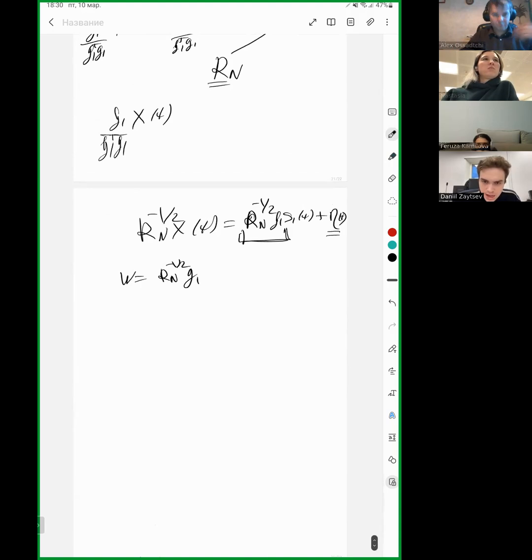Of course, you can reformulate beamformers for cases where you never have a single source. You always have multiple sources, right? And all you have to do is somehow distribute the degrees of freedom that you have, your 100 sensors, or 200 sensors, 100 degrees of freedom, in order to not only emphasize the source of interest, but also suppress the interference sources, right?